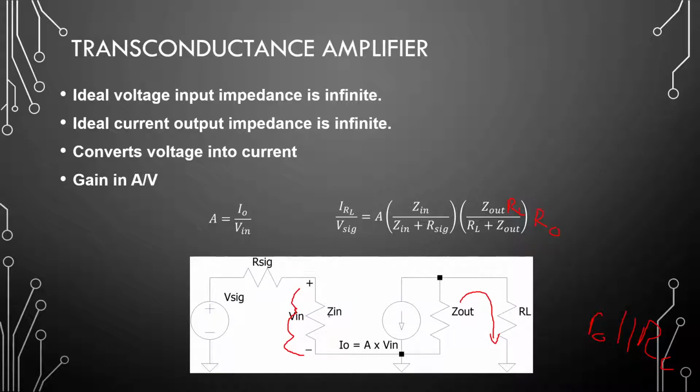So you can convert between your amplifier types, whether you're looking at transconductance or voltage gain, and always remember that transconductance is in amps per volt. So amps per volt, and if we multiply that with volts over amps, which is a resistance, we get our output voltage, our voltage amplification.